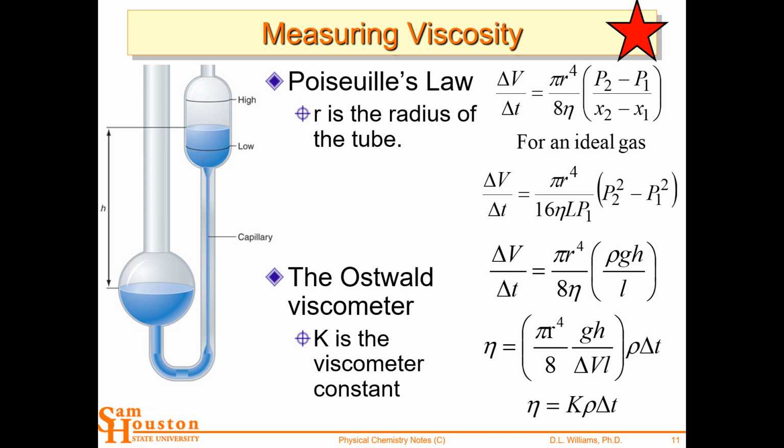Okay, so all our water pressure in the city is just by the fact that we have these towers, and that's providing water pressure through all of our pipes. And so it's pretty straightforward. The length of the pipe is linked from the reservoir to like the source or towards. Yeah, so you could, if you just had a straight, half-inch pipe from that water tower to your house, and you knew the length of that, and you knew the gravity and how high it was, that's your pressure head, you could calculate the flow.